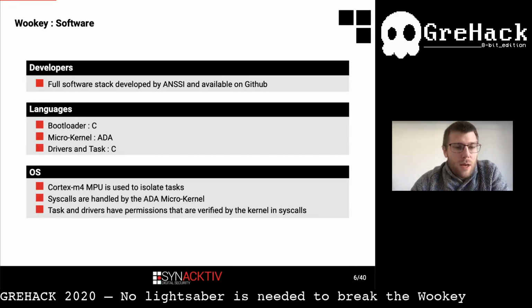Drivers and tasks are written in C code and run in a non-privileged mode. The kernel uses the memory protection unit to implement task isolation, and the syscalls are handled in ADA, and some permissions are applied at build time on the task, and the syscall checks this permission at every call.